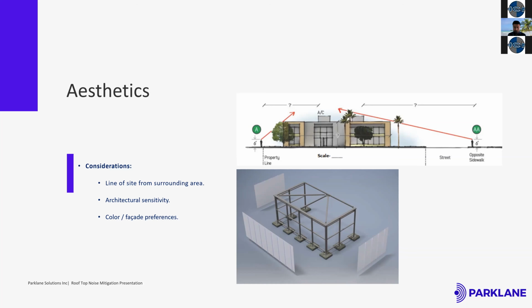Now in this case, each room, depending on what kind of room or facility it is, will have a specific NC rating, which is dictated by OSHA, or even ASHRAE has some specific NC rating for a library or a gymnasium or a classroom and such. You'll have a specific NC rating that you need to meet. An NC rating is essentially noise levels at each individual octave band spectra. And if you exceed that, then you're going up another NC level.